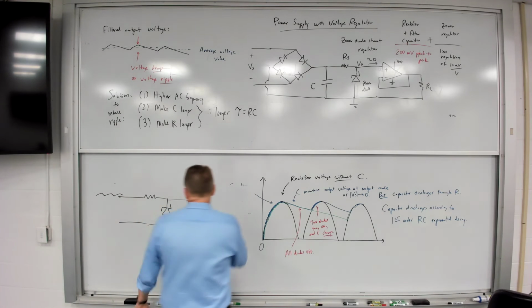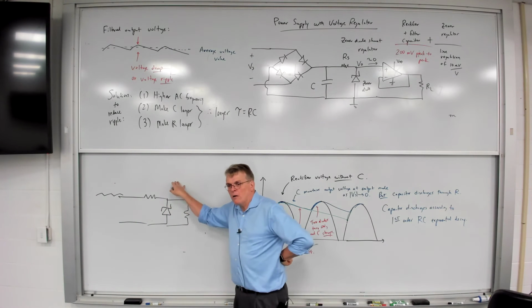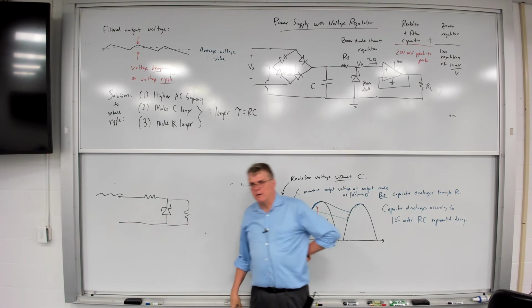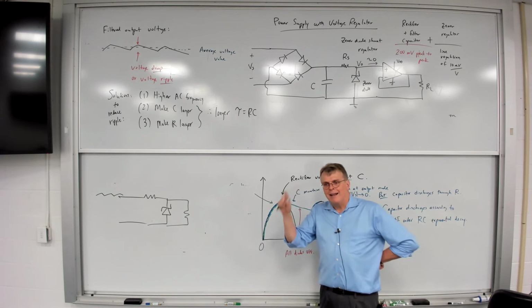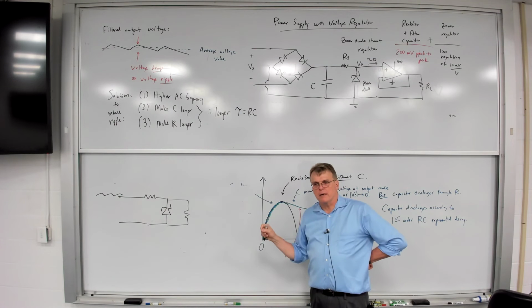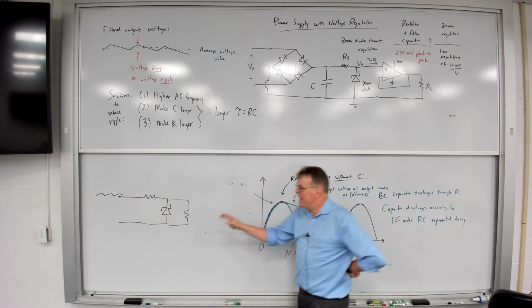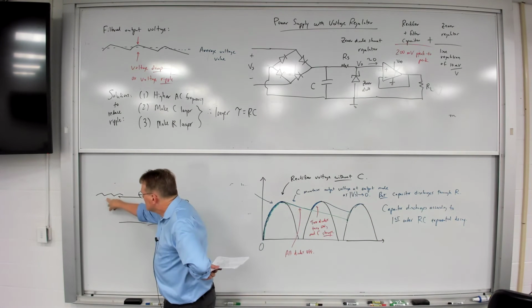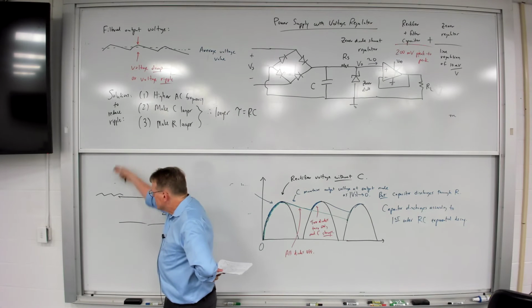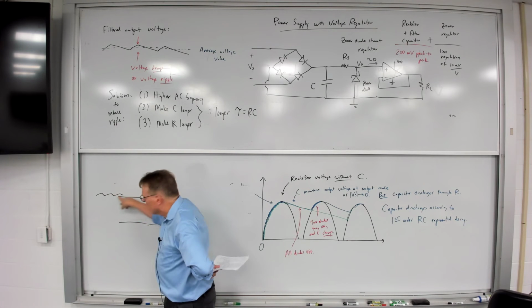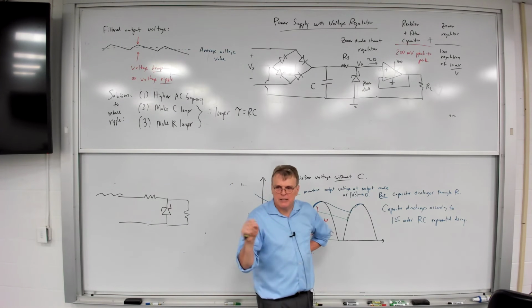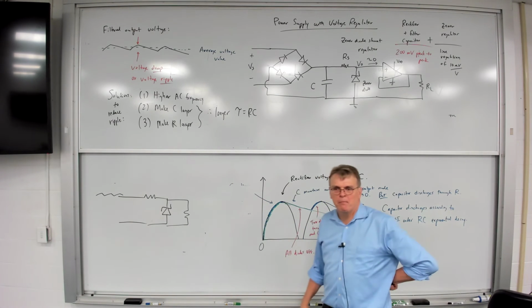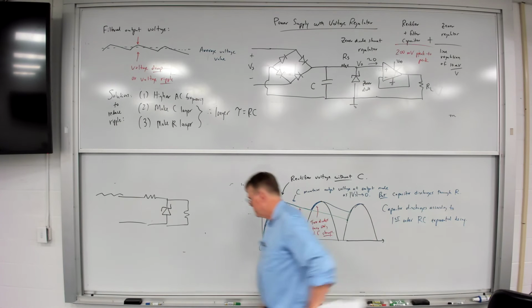And you can actually prove this works in either the large signal or the small signal domain. Do that calculation. Look back in your notes when we did line and load regulation for a Zener diode. Nothing's different here, except now the input voltage variation we're seeing is not some huge swing, it's the actual ripple. And so we're now rejecting that ripple. But the same line regulation principle still holds. Okay?